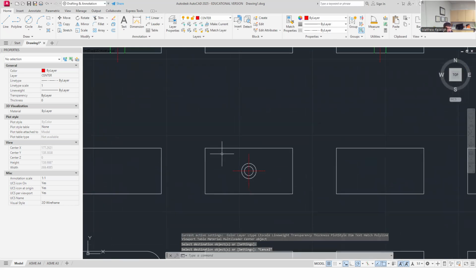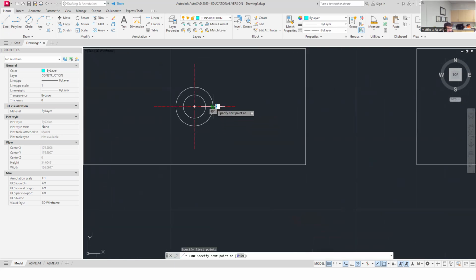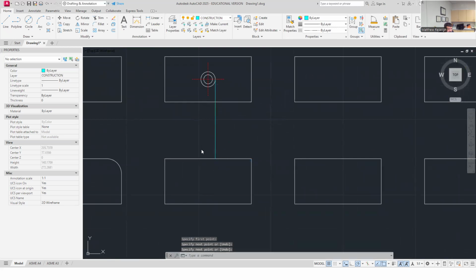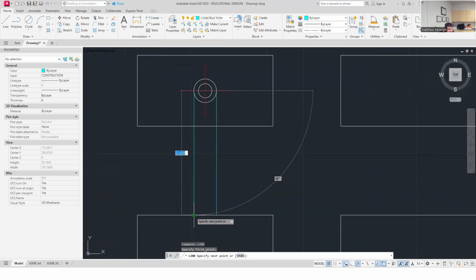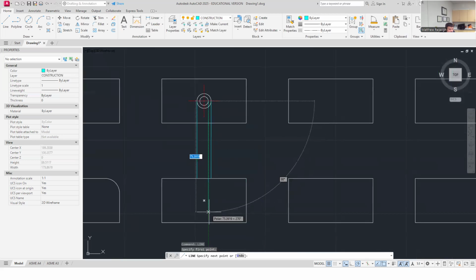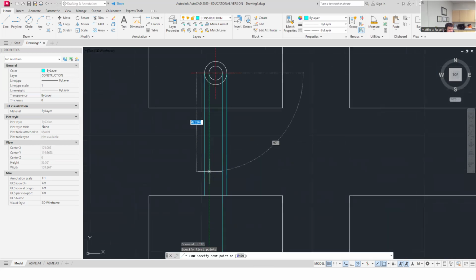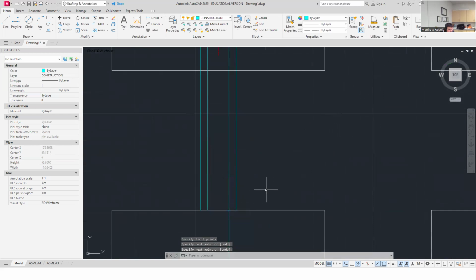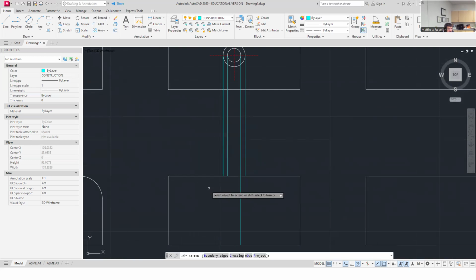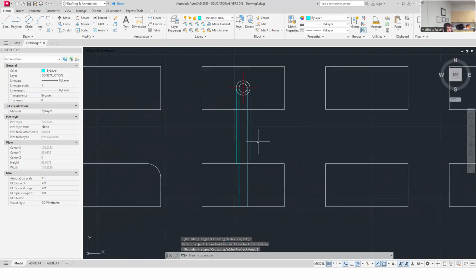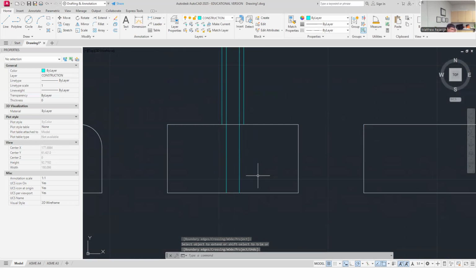It's not that big of a time saver, but we'll project down a little bit of construction work here. The quadrants, I want to project them down, make them a rectangle. That's the larger diameter ones. There's my 0, perpendicular, enter. Inside bore, I'll pull it down and through. Sorry, I didn't pull that one down and through. I should. I'll extend it. I love the extend command. Bam. Okay. Keeps things orthographically aligned. And then it's just 2 millimeters deep.